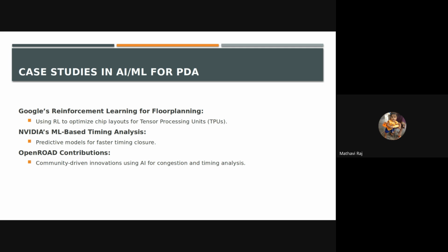In RL, the algorithm learns from experience, progressively improving the placement of components on the chip based on feedback from system performance. The algorithm searches for an optimal component layout that minimizes interconnect lengths, optimizes power distribution, and improves chip performance. RL can enable Google to accelerate the floor planning process, producing designs that are more efficient and less power hungry, crucial for high performance chips like TPUs.